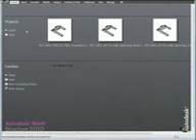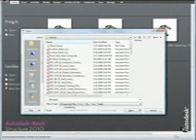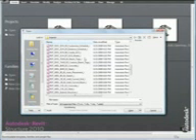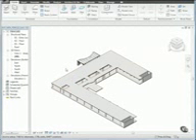Click the menu browser and select Open. Then, from the Training Files Imperial folder, open the file rstmdl-fdn02 Isolated Foundation. Then, open the View 01 Entry Level Structural Plan and zoom in to the northwest corner of the structure.